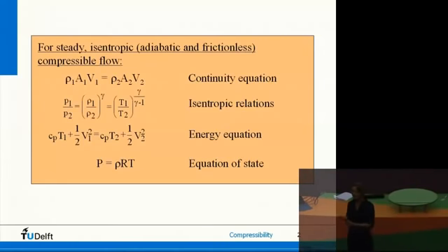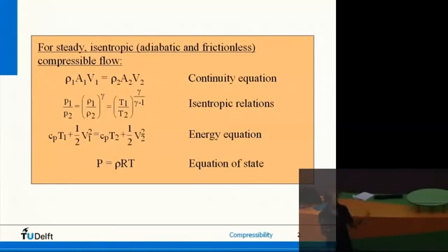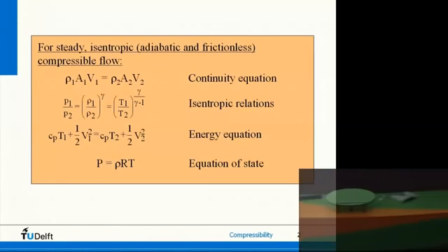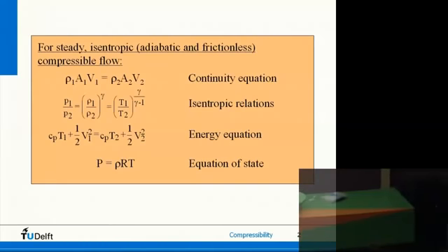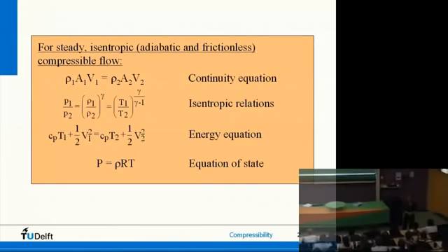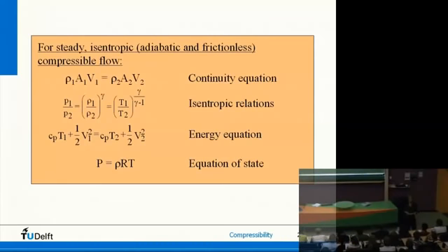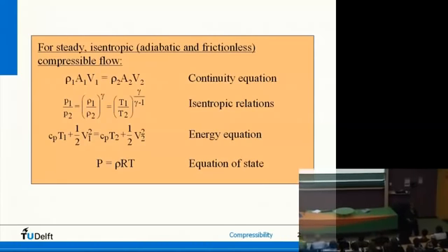And actually, if your flow is fast, supersonic, transonic, you have pressure and density changes such that the temperature does change in your flow, through P is rho RT. It can expand very much, so the density can drop a lot, and then something will happen to the temperature as well. So please bear in mind, isentropic flow means there's no heat added or subtracted, but the temperature can change. And the other thing is that it should be reversible so that dissipative effects can be neglected.